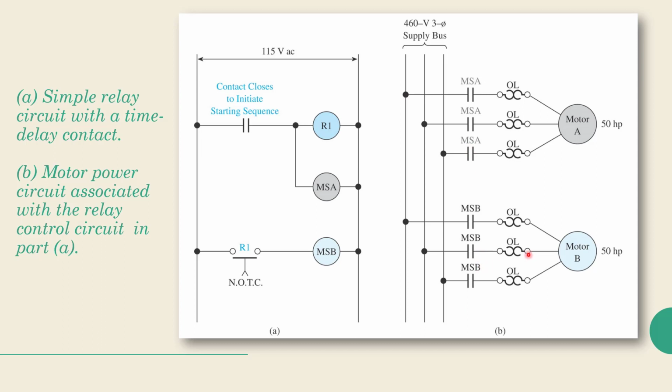If you've ever gone through a car wash that has the blowers blow the water off, if you listen, when those start up, you're going to hear those motors start one at a time for that exact reason. You'll hear one start, and in a little bit the other one will start, and once it's going, then the other one will start, and that's to prevent that inrush current from happening all at once.